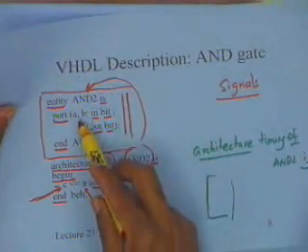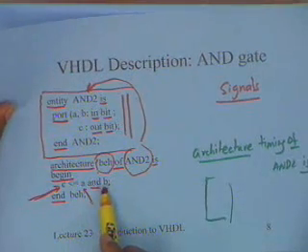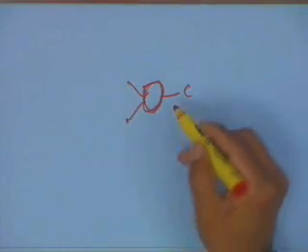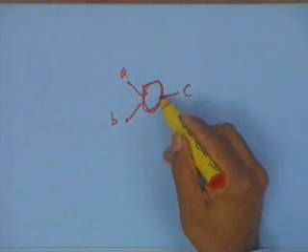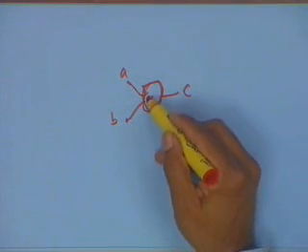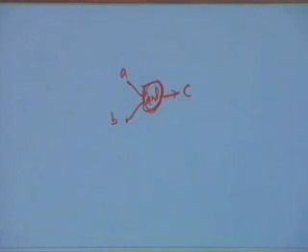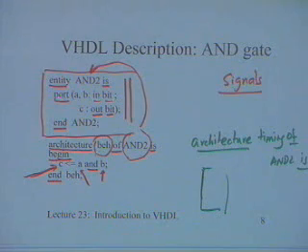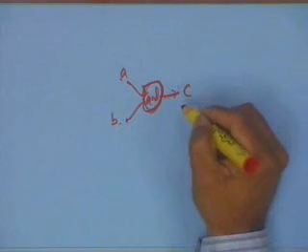So all these declarations that I made here are also visible here, and A and B are input signals of special type, which are ports, input ports. C is an output port. So I need to compute A and B, and in this case of course it's an AND function. It's a simple function, and then there is a driver for C. But once I declare this, the implication is whenever there is any change in either A or B, automatically C will be updated.